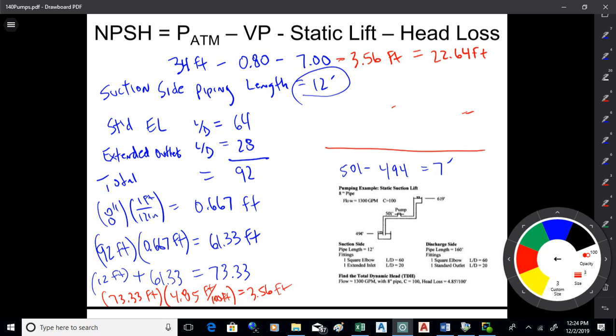You might need one to isolate the pump, but hopefully that's a gate valve wide open so it doesn't cause much head loss. You don't want a butterfly valve back there because it's going to create a lot of head loss, and that just creates more problems for cavitation. The other thing you look for is leaking fittings, because if you're sucking air into that water going up into your pipe, those air bubbles are going to collapse and cause you problems too. So those are just some of the things you might be looking at, okay?